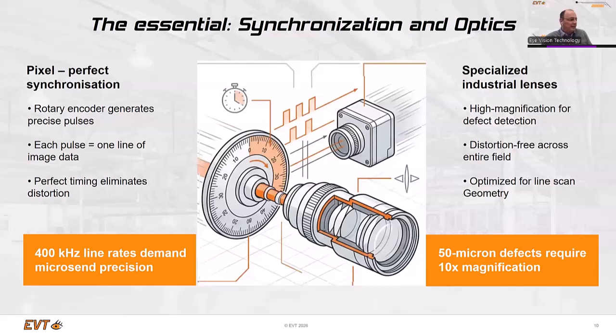The only limit is finally the line scan rate of the camera, and of course the light you can apply to the surface. This sounds somewhat easy, but if you have very high line scan rates, you need very high powered light sources, which sometimes cause damage to the material, depending on the material.